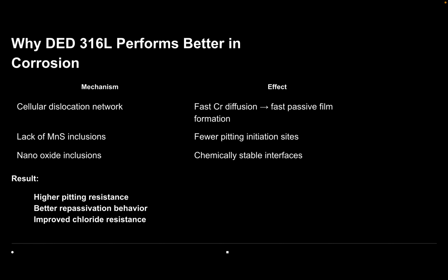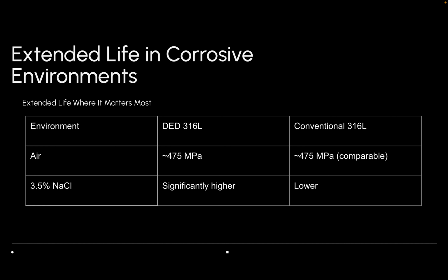And DED 316L shows improved corrosion resistance due to the absence of MnS inclusions and rapid passive film formation. This is particularly important in chloride-rich environments. Extended life in corrosive environments.